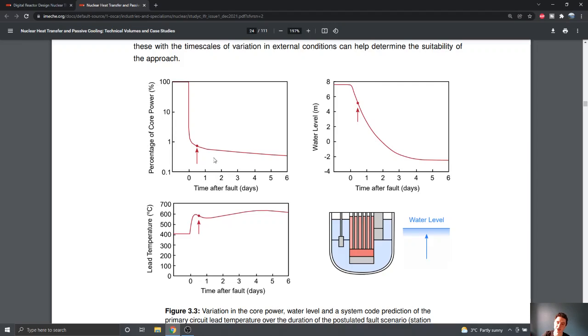And this is the heat that we actually have to deal with when we're thinking about the fault that the nuclear reactor undergoes, because if you were to leave that heat uncontrolled, of course, things would continue to heat up, and that's where we could get problems with the reactor. And what we can see is that, after a few hours, we're getting radioactive decay now, and of course that heat will slowly decrease over time, and as many of you will know, that will be an exponential decay for the radioactive decay heat there. But for us as engineers, 1% of the initial power is still a lot of thermal energy that's coming out of the reactor, and this is the heat we need to deal with.